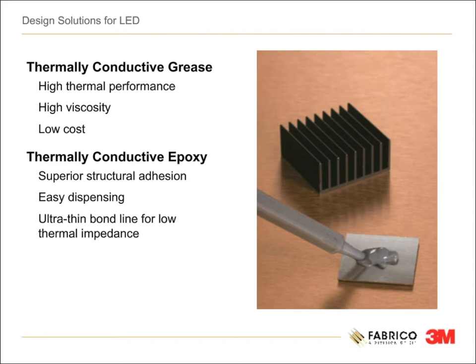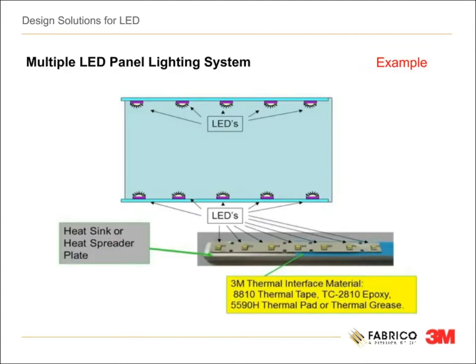Thermally conductive epoxies offer permanent attachment for applications that will never require disassembly. Thermally conductive grease is effective, but hard to dispense manually in a high-scale production environment and still requires mechanical fasteners. In LED displays, several different TIMs may be utilized within a single application. Over to you, David.